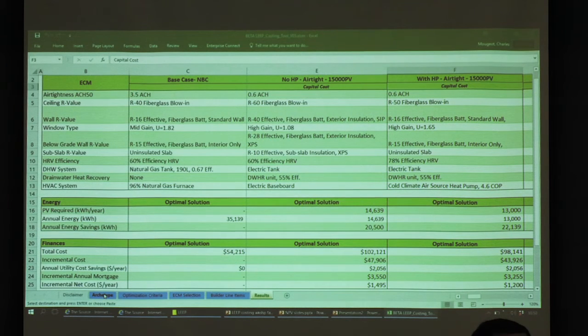Yeah. And the other thing is, I guess, because your air source heat pump is going to provide you with heating as well as cooling, it can be a difficult balance adjusting your sizing for your heating requirements and then adjusting your sizing for your cooling requirements. And if it's variable, then that's great. But if it's not variable, then you can definitely experience some comfort issues because it's oversized for heating or it's oversized for cooling, and so you're going to have short cycling on your flow and stuff like that.